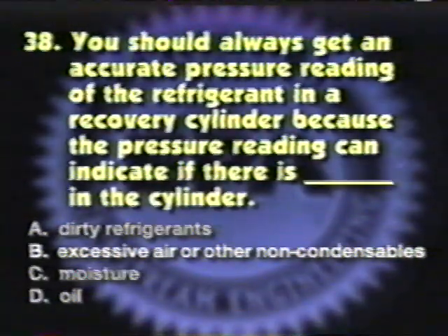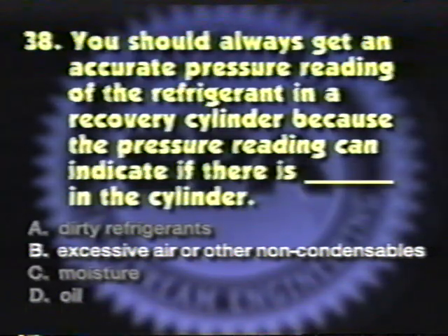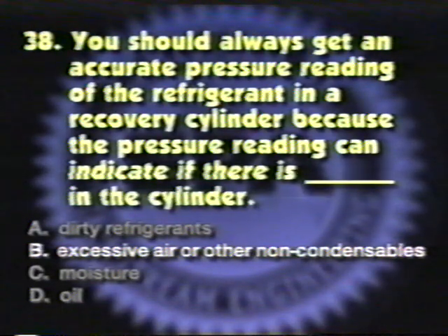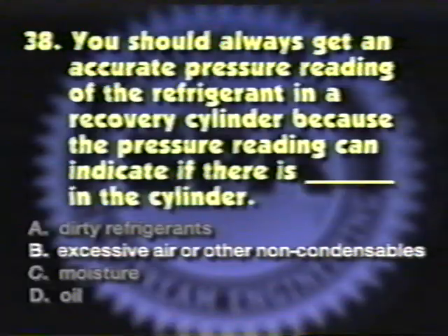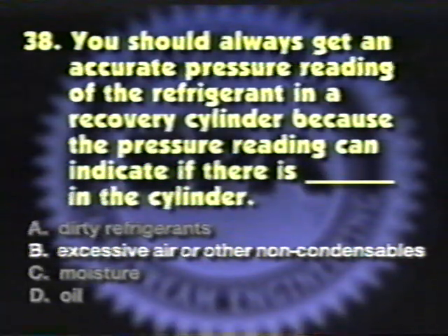The correct answer is B. Accurate pressure reading of the refrigerant inside a recovery cylinder is necessary to determine if excessive air or other non-condensables are in the cylinder.